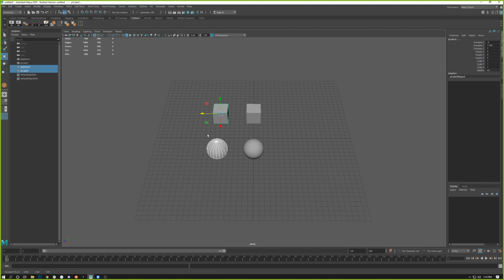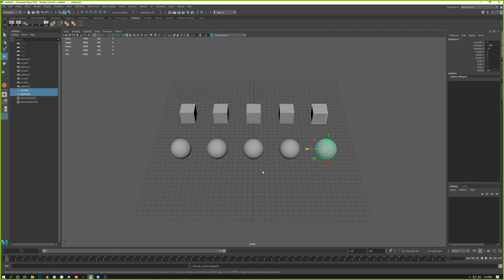So it's not a big deal either way. So hit Shift D, and you see it duplicates it again. So let's go the other direction to showcase this. Control D, holding down X to grid snap, and then I'm going to hit Shift D. And as long as it's the last thing that you do, you will always keep the spacing the same.